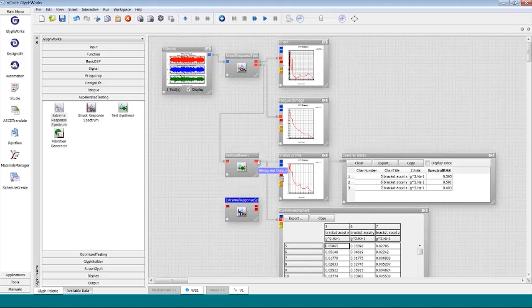What I'm getting at here is I can take this accelerated PSD, plug it in here, and I can turn on and calculate the same two things I used to quantify shock and damage from the measured data. I can do that in exactly the same way for my shaker profile. So this will allow me to test, is this test really equivalent damage? And is it reasonable shock?